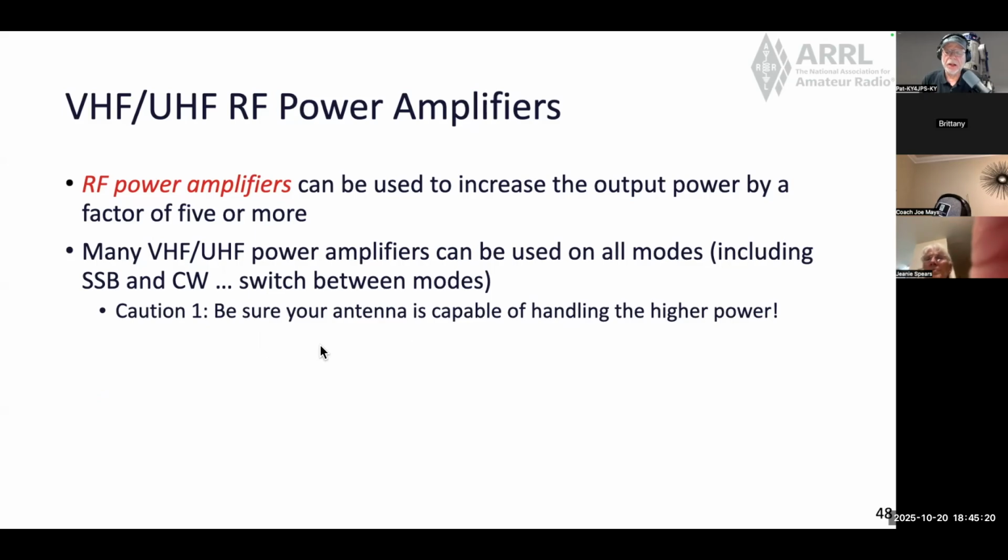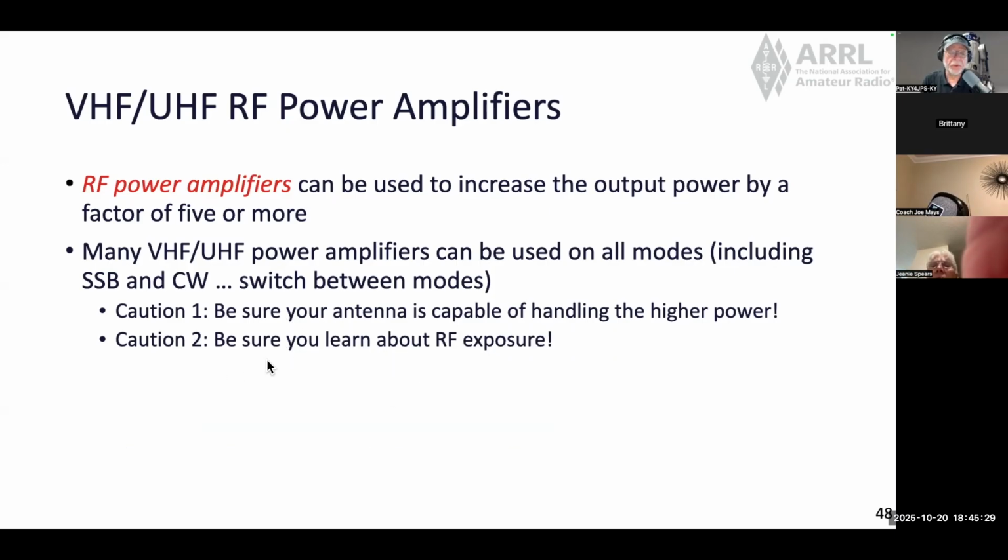You can literally burn up an antenna or burn up components of the antenna if you try to run too much power through it. And another thing you want to be sure that you learn about as you use amplifiers is about radio frequency exposure. You don't want to have too much radio frequency exposure to yourself, even though it's not radiation like the kind that causes cancer. You still want to be aware of the exposure.